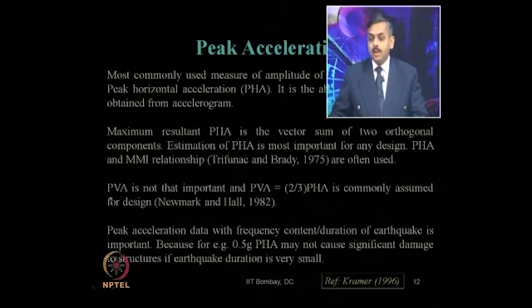And PVA, that is peak vertical acceleration, was considered not that important, but nowadays researchers differ from this statement. This statement was given by Newmark and Hall way back in 1982, but after 1982 several research works have been conducted, and it has been shown that yes, PHA is the most important, but it does not mean that PVA is not important.